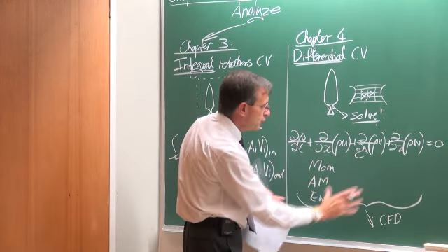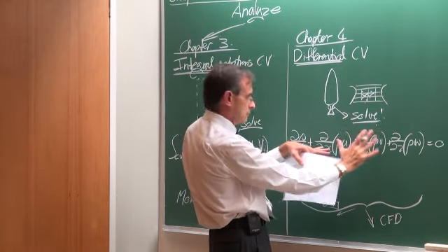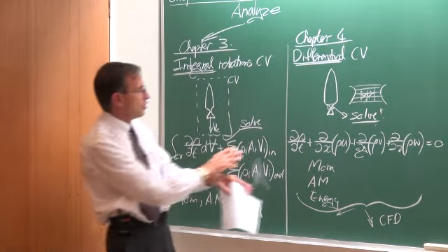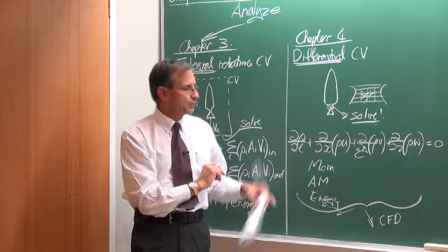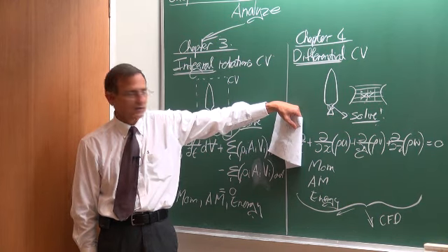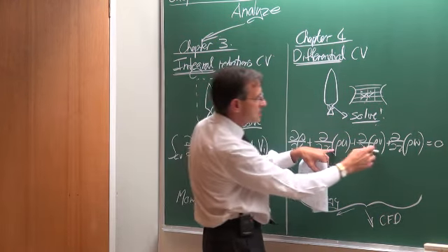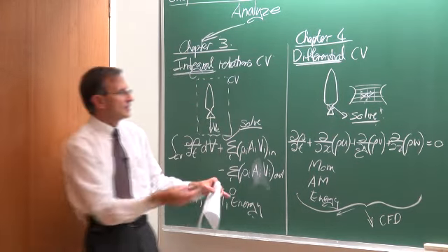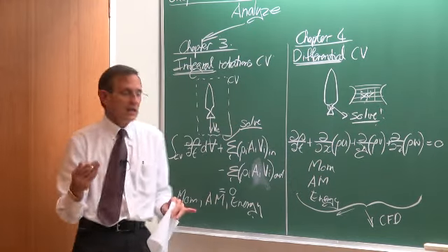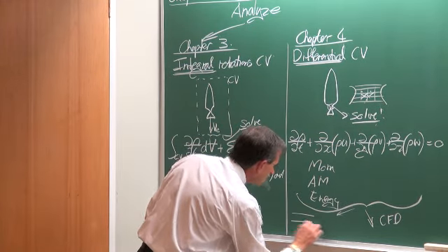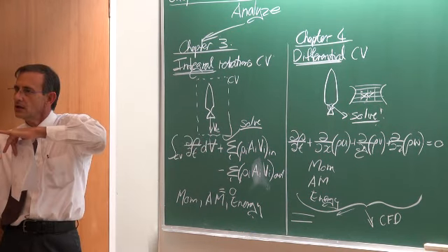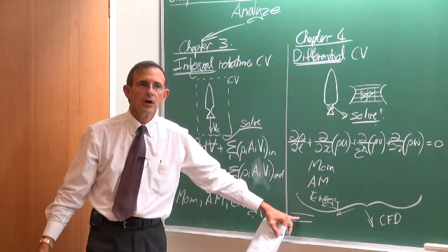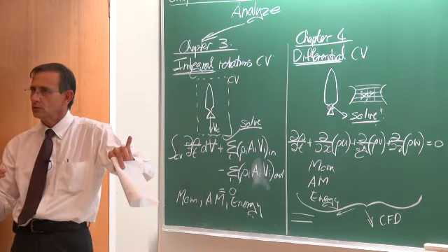So, a lot of work has been done where, firstly, assumptions were made in terms of practical problems. For example, let's consider steady state problems. So we throw out that term. We would say, let's suppose the density is constant, it is one-dimensional, etc. And then these equations were used in geometries like, for example, between two flat plates to derive the velocity distributions, or through a pipe.